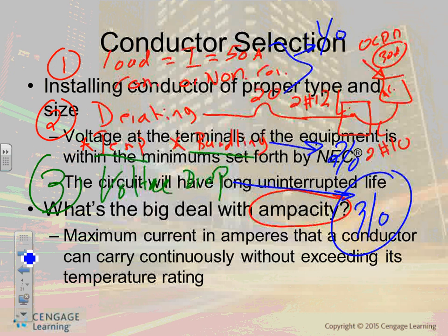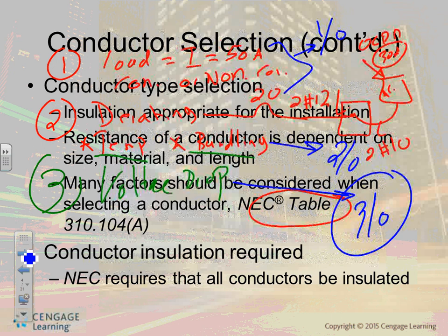Now, a smart engineer and a designer would not group more than 6 circuits in a pipe, so the derating becomes not a big deal. You don't worry about the derating if it's up to 6 circuits based on the derating factor. And if you're going outside, don't bundle, because outside becomes higher temperature, especially in the southern states. Then you don't have to worry about step number 2, right? Now step number 1, no problem: continuous, non-continuous, and worry about voltage drop. So if you're on the border, always go up because of voltage drop. That's to summarize the whole system, gentlemen.